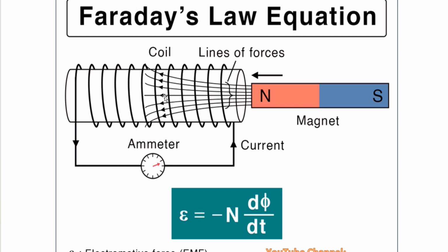On the contrary, once you have inserted the magnet and it is here inside the coil, if you keep it stationary inside this coil, then there is no deflection in this ammeter or galvanometer. But when you quickly draw it out, then also the deflection is there, and you will face a resistance once again when you are trying to take it out. Because when you are trying to take it out, the flux linkages with the conductors of this coil again induce EMF, and that EMF causes induced current, and this current again creates the electromagnet.